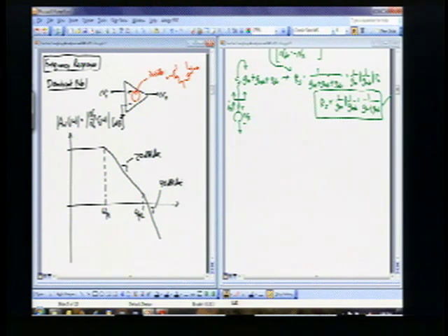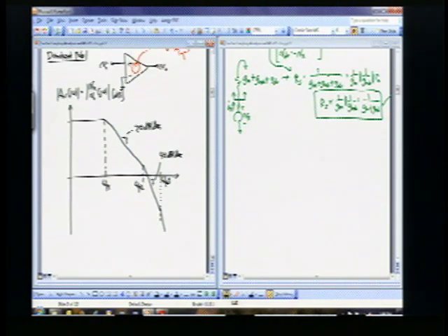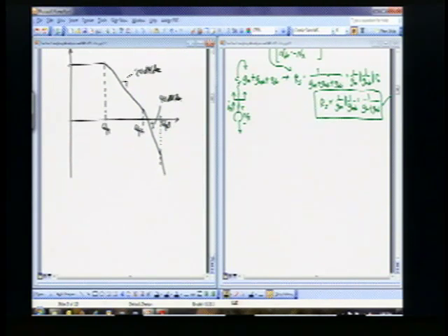I'm just adding 20 dB per decade to the original decrease rate. Okay, and it can keep going beyond this. So I could have yet another pole here, which could be my omega P3, and then that would start decreasing at an even faster rate due to this other pole. All right? So just simple Bode plot formulations there.